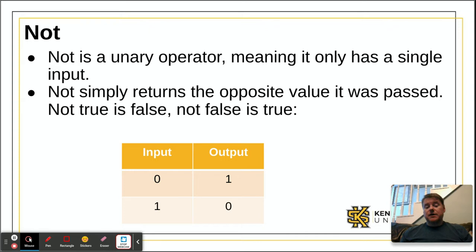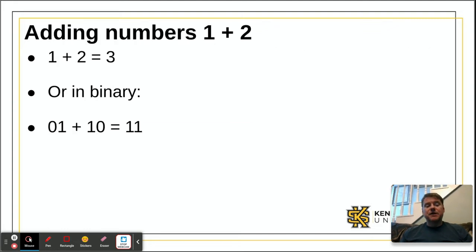All right, so truth table for that one's very simple. Input 0, output 1. Input 1, output 0. There's really no way that I can simplify that beyond that. So that gave me 3 gates. We've talked about AND, OR, and NOT.